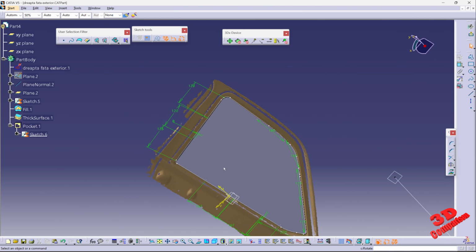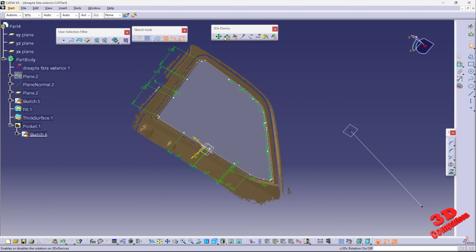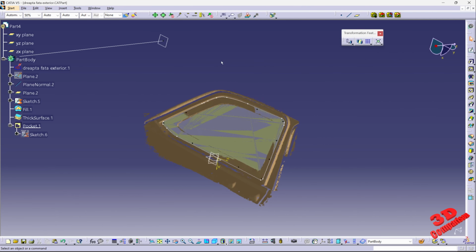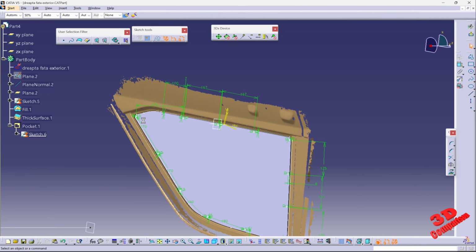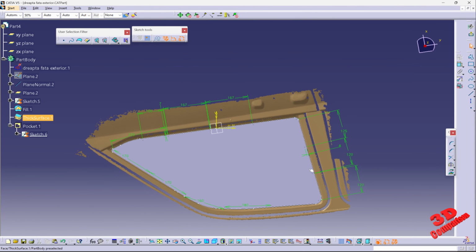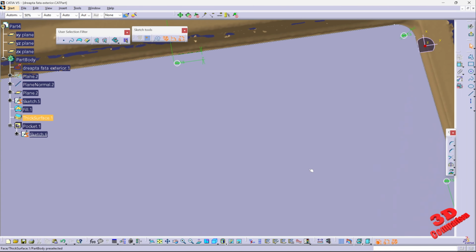But usually within the newer versions of CATIA, the add-on for the 3D mouse will automatically keep the rotation locked while we are within a sketch. But for example, if I leave that sketch, we're going to see that over here, the 3DX device will no longer keep that rotation locked. So I can easily rotate around the part over here. But while I'm within a sketch, so I double click on that, we're going to see that this will automatically keep the rotation locked. So we can just zoom in and navigate the part like that.